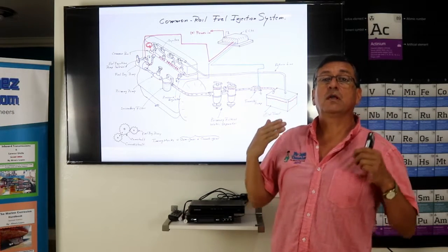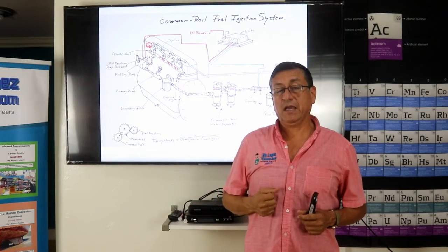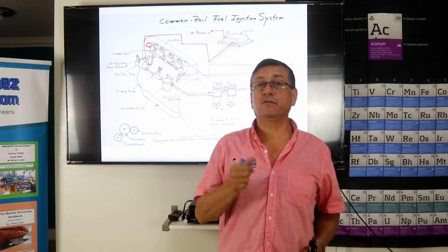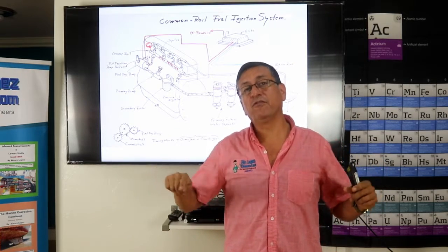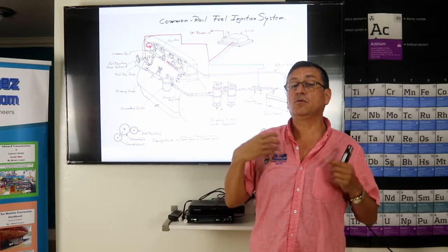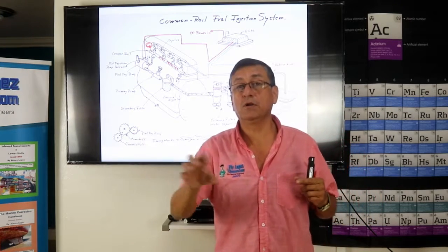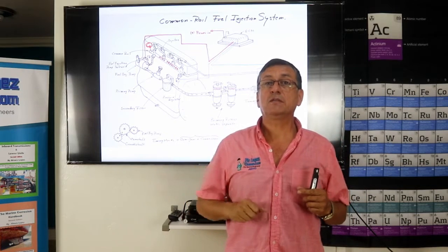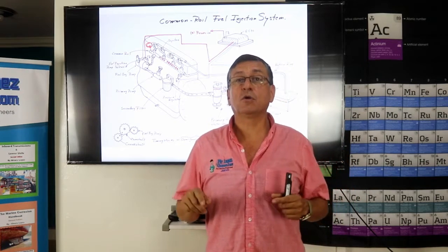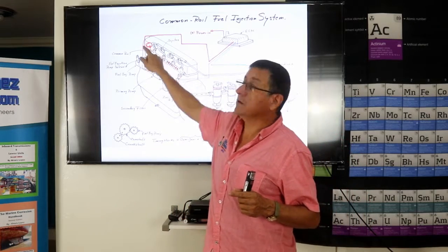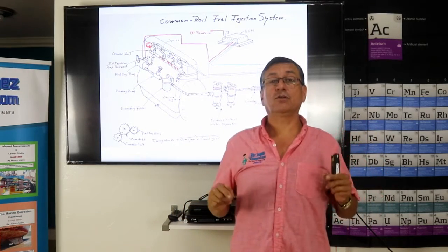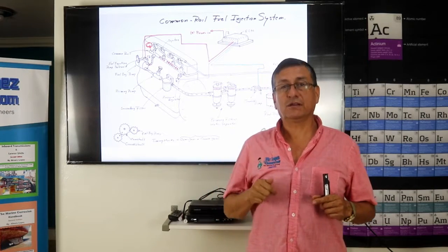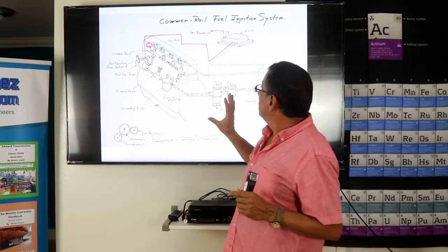It is important. If you are the engineer of a big boat, a mega yacht, you enter the engine room, you check the water separator filter, you verify if the fluid is passing. You can identify if you don't have bubbles in the system. You can identify if you don't have water or sediments, and additionally you check the common rail of each engine and verify the pressure according to the manufacturer's specification, according to the recommendation in this particular service manual.